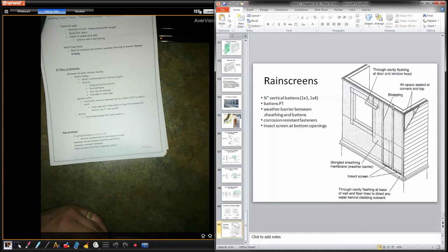But you don't want to leave that top open because air can actually go right into the attic. So what some people do is they leave gaps on the strapping in these locations to allow the air to flow through. Kind of create like a loop, so it can move from one cavity to the other, allow for some airflow to come through. 3/4 inch battens, 1x3 or 1x4. So a lot of times 1x3 in these locations, at the corners, sometimes even a 1x6.